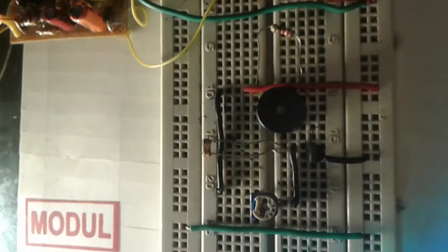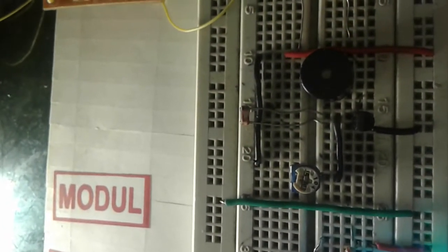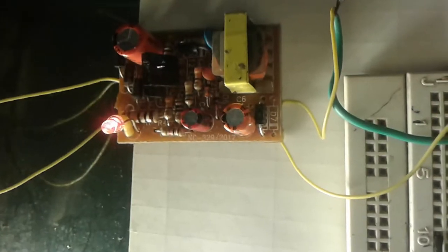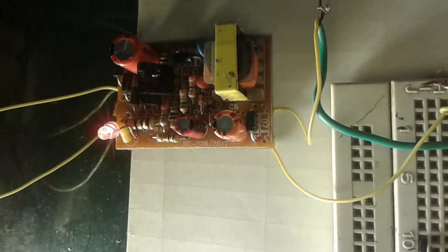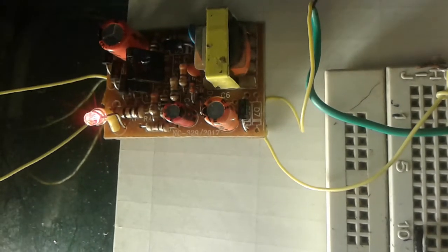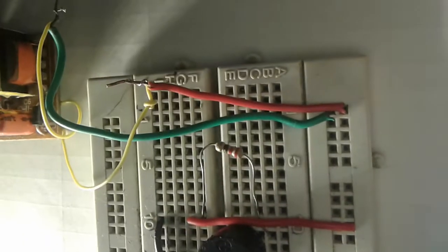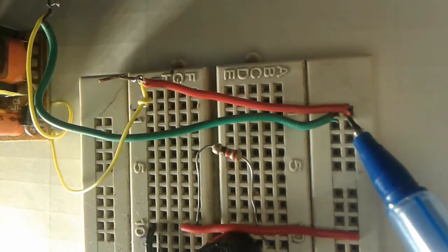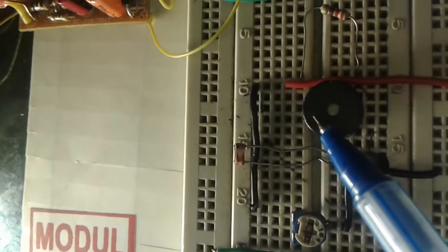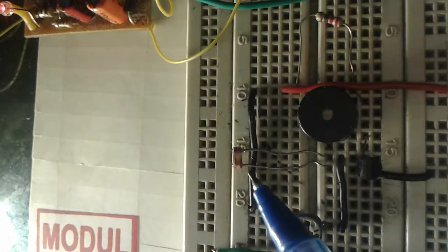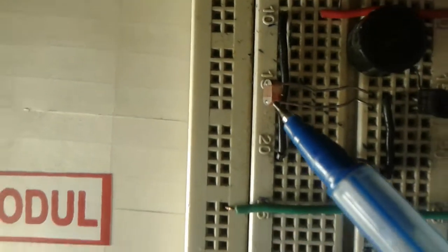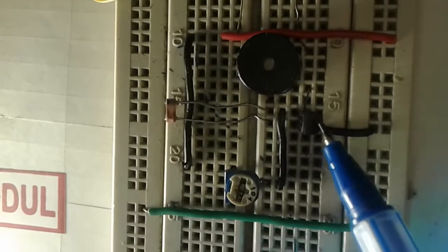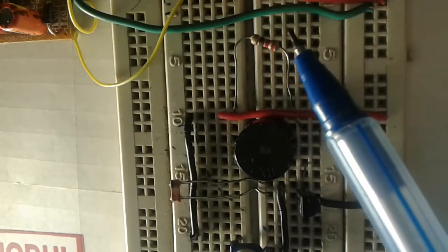Here we go. This is the working circuit of that dark sensor circuit. Okay, so here is the power supply. There is the indicator LED. You can see it is glowing, which means the power is supplied to the circuit. And these are the terminals. Light green is negative, and here red is positive. This is the buzzer which is showing the output. This is the LDR which is acting as a light sensor, the variable resistance, the transistor, and this simple resistance.